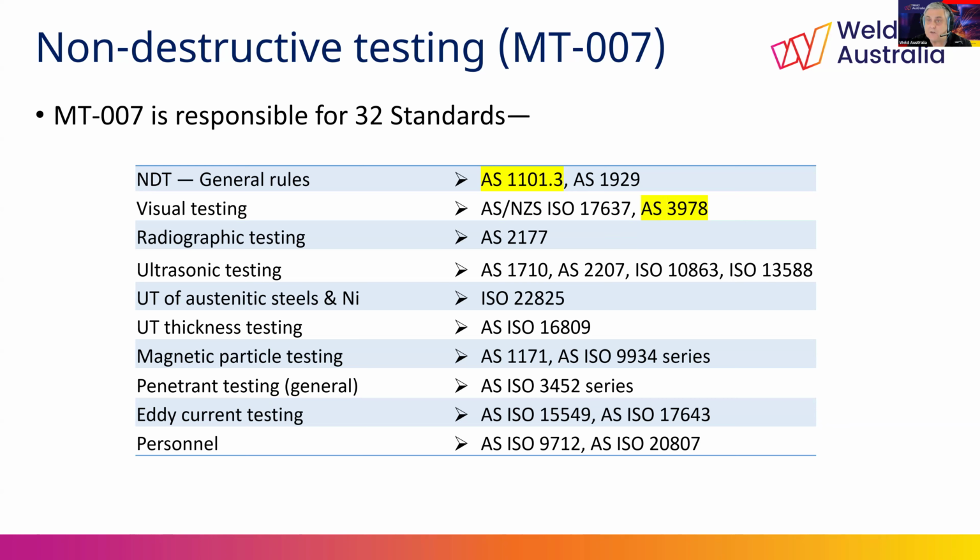If all they're doing is loading items into a jig and pushing the go button and have no other controls, then there is a very strong view that those people need to be competent at what they're doing, but they don't necessarily need to be regarded or qualified as a welder. The welder qualification will only come in if they have any form of input or control over any welding parameter, including the position of the welding head, for example.